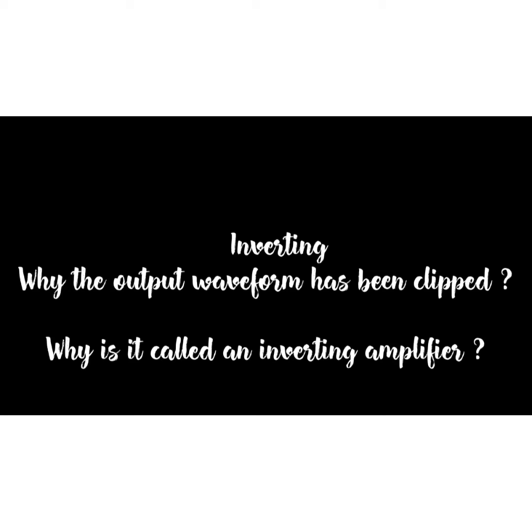And the second is, why is it called an inverting amplifier? It is called an inverting amplifier because the op amplifier changes the phase angle of the output signal by exactly 180 degrees with respect to the input signal.